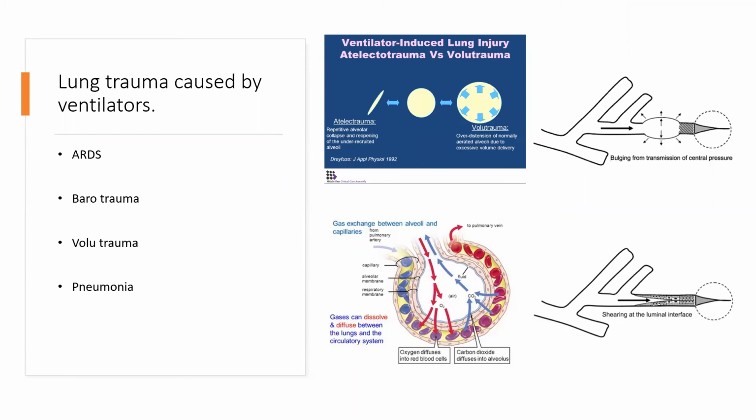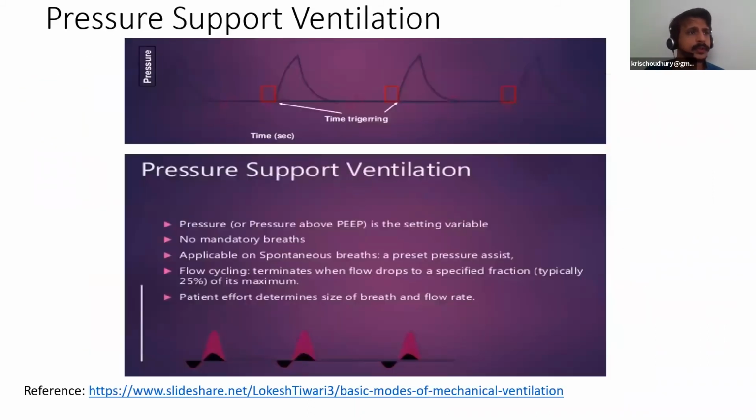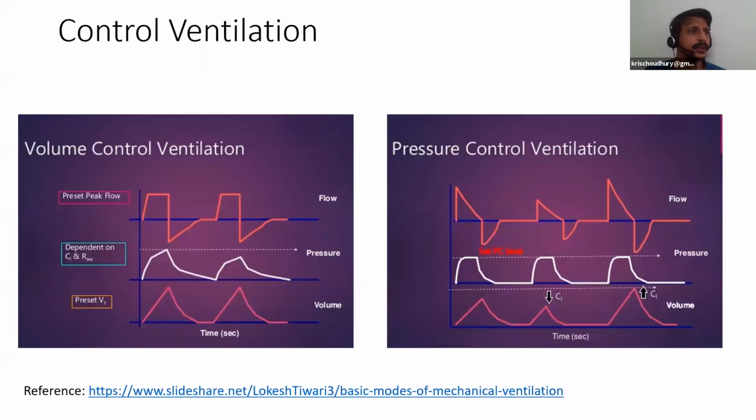What do you think about this whole open source ventilators that people are trying to develop using simple, alternative sensors? So most of these open source ventilators, if I come back here, would work on any one of these control ventilation kinds of setup, right? And they can work very well if the patient is sedated completely or is in a coma, and you have to keep him alive, and there is no lung function at all. So you have either lung volume control or pressure control. Most of these low cost ventilators would essentially stop at this mode over here.